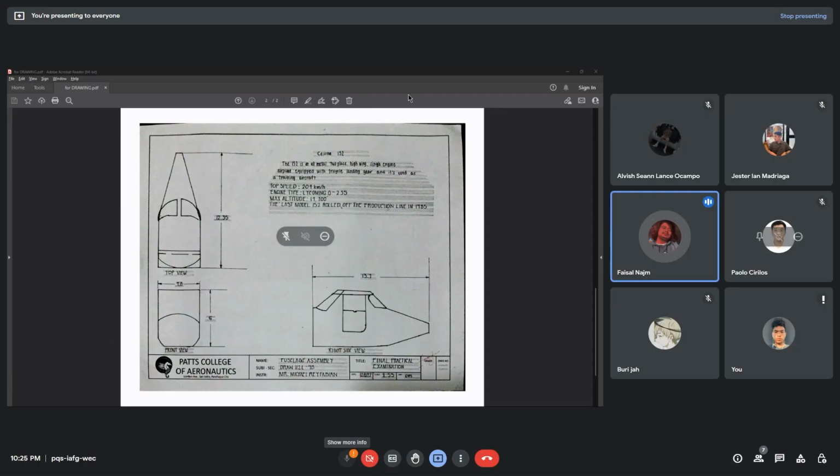And here I'm going to talk about the main metal that has been used in the construction of the airframe of the Cessna 152. The metal that has been used is aluminum. It has a good weight to strength ratio. It is resistant to UV damage and also costs less, which makes it a perfect material in aircraft construction. The fuselage is semi-monocoque and has two seats. The Cessna 152 is a stressed skin aircraft. It has vertical bulkheads joined by the longerons running the length of the fuselage.